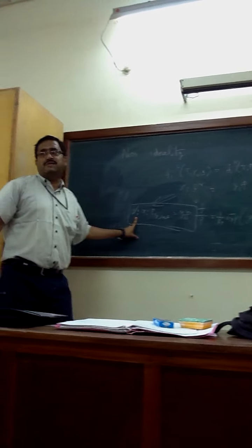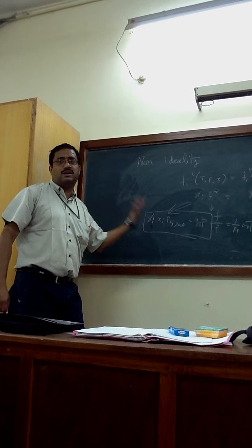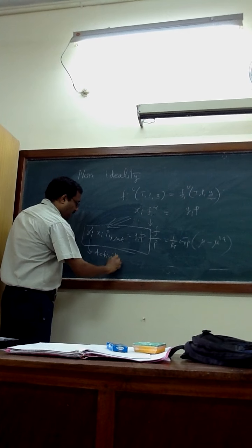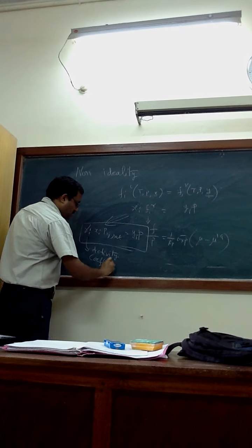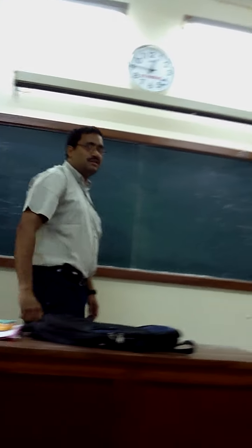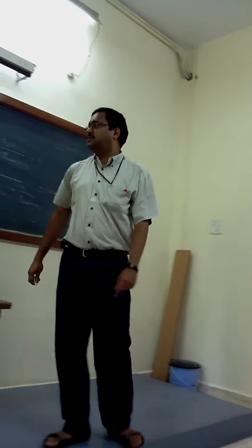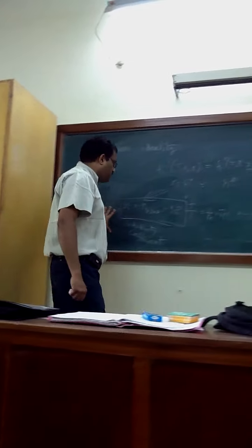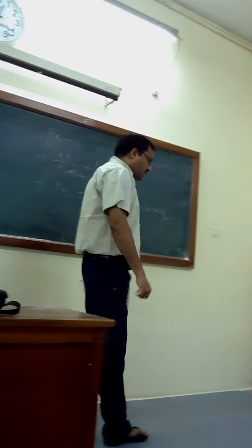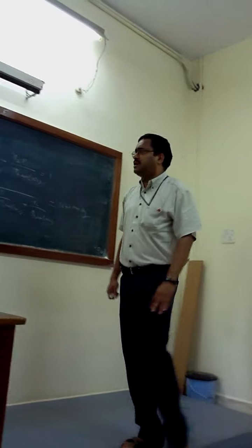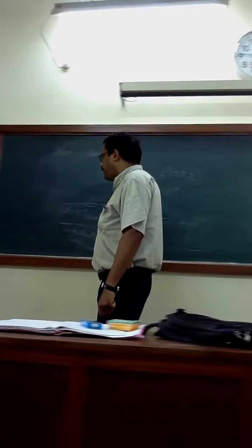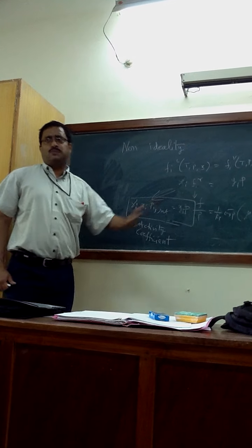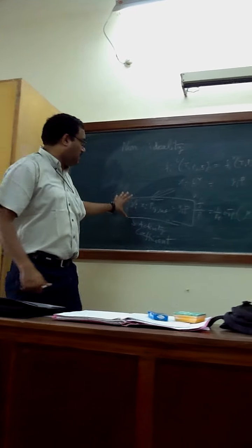This is called the activity coefficient. So now you can see the fundamental rationale for the activity coefficient. This means the liquid phase is non-ideal, and this activity coefficient model is valid for moderate pressure. At high pressure it is not valid again. So the gas phase will behave ideally, but the liquid phase will not. In that case you have a modified principle, which may be called modified Raoult's law. I don't know what it should be called, but this is the equation you can get.